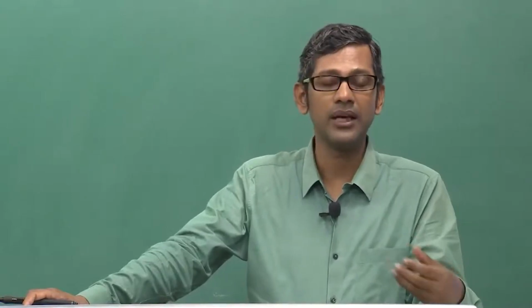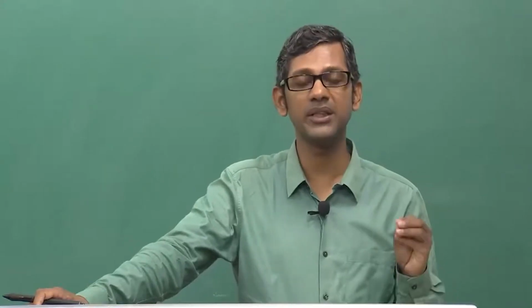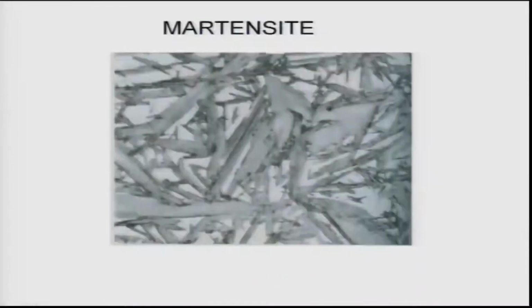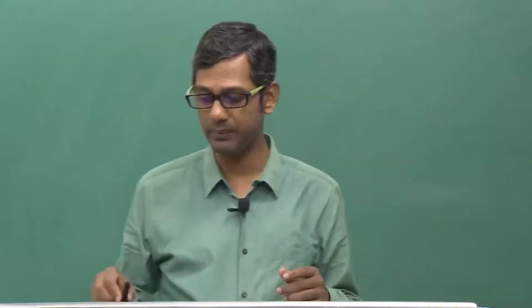So we normally get confused with the morphology of the upper bainites, and that is why you need to look at it crystallographically under a transmission electron microscope, look at what kind of crystallographic coincidence relationship it has with the prior gamma grains or with the cementite. Only then can you clearly say this is bainite and not pearlite. But lower bainite is distinctly visible under the microscope because it has precipitation of Fe3C inside these supersaturated alpha grains which have shot out from the gamma grain boundaries. Okay, so I will just stop here for the bainitic discussion.